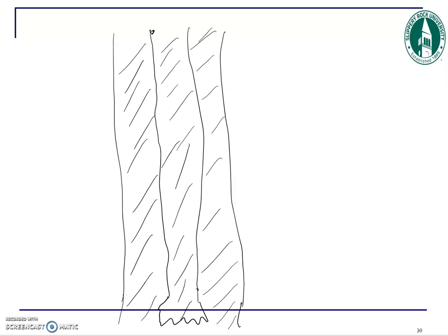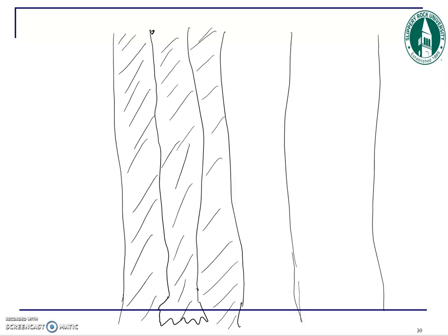You want to stop your drilling, take out your drill string system, and change the bit. What happens to the level of mud inside the wellbore? Initially, this is the bottom. For both of these, this is just the same hole. You just remove the drill string and drill bit from it to change the drill bit.